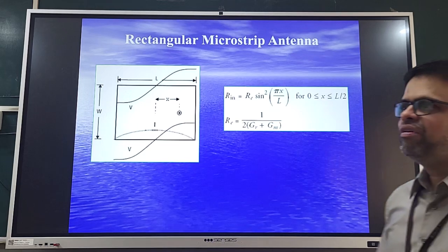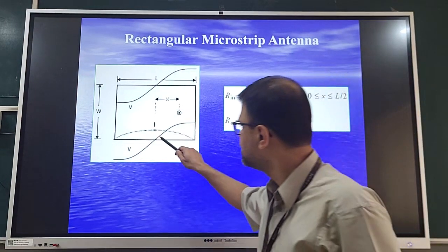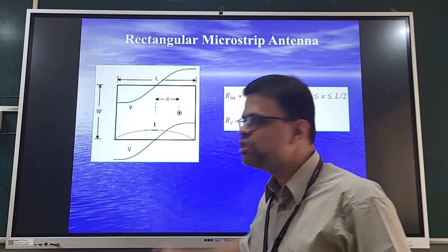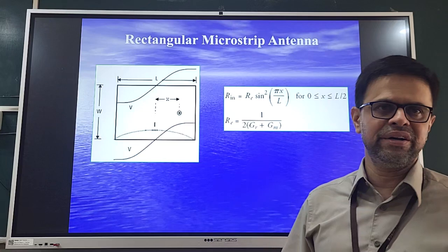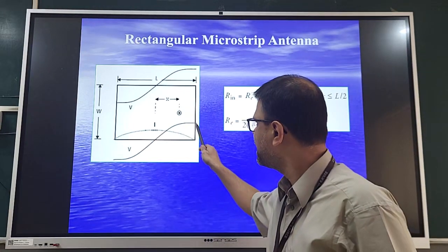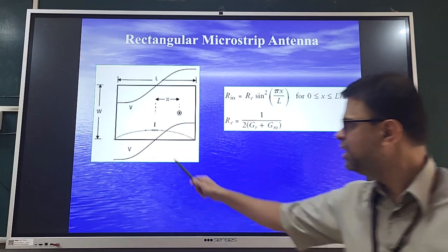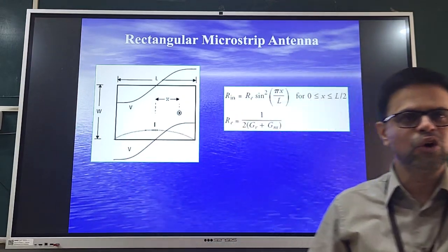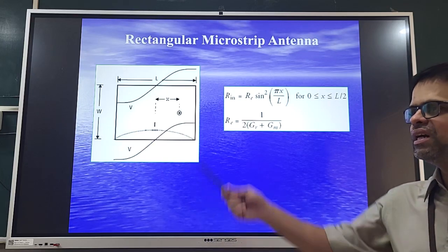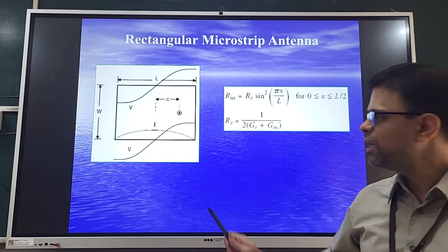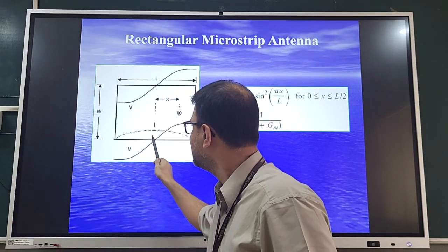Impedance plot will be following the voltage plot. Okay, so since the current is maximum, impedance will be 0 here. As it is an open circuit over here, impedance will be maximum here. Okay, impedance will be maximum here. Here, impedance is maximum, but it has not gone negative maximum. Why? Current voltage polarity has reduced, but the current is in the same direction. So the impedance is maximum, but it will be like this. See, the plot will be like this.